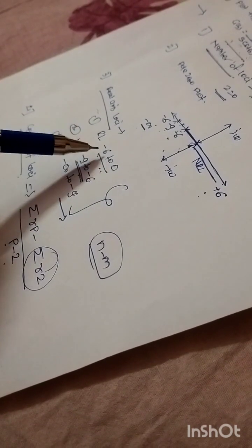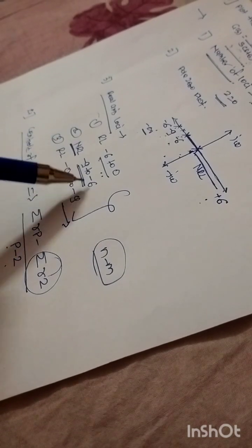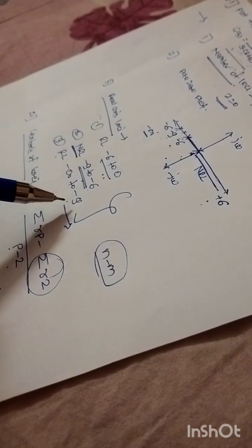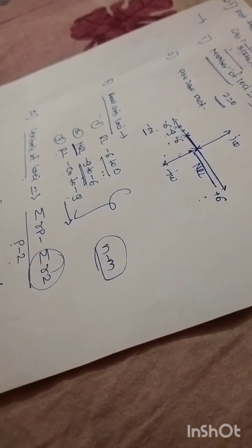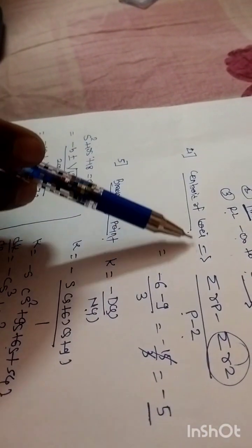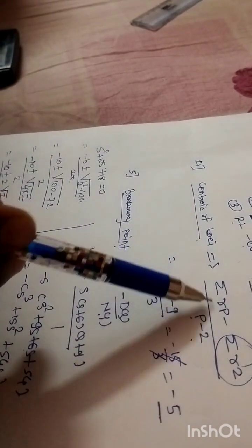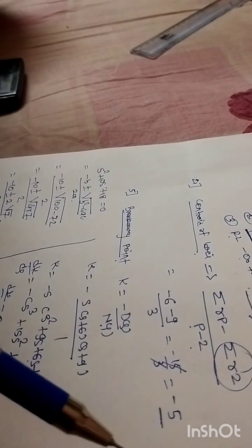So accordingly, these three real axis loci are defined, in which there will be a presence of root locus between -6 to 0. There will be no root locus between -9 to -6. There will be a presence of root locus between -infinity to -9, because always one pole by default is present at minus infinity. Step number 4, we need to determine the intersection point on this real axis. The name given to this intersection point is centroid, which is given by this standard formula, summation of real part of poles minus real part of zeros upon p minus z. So it will become -5.